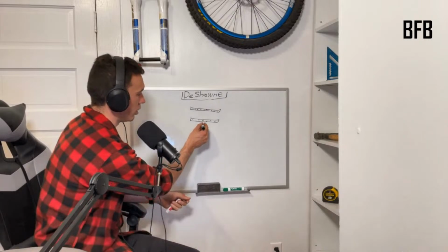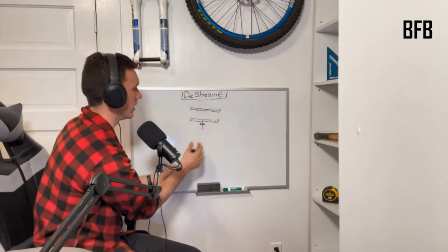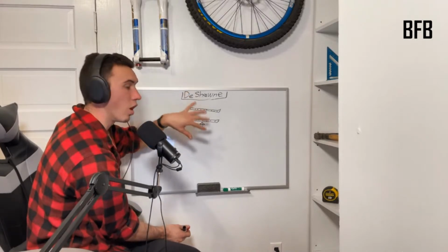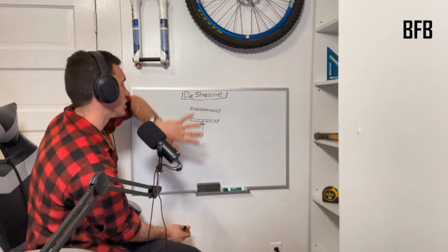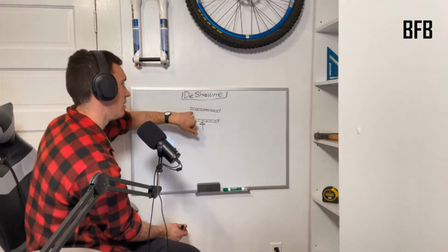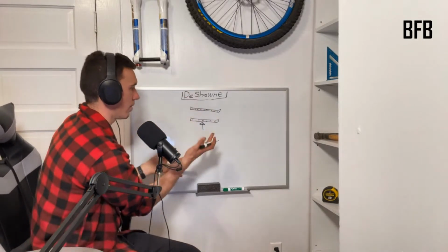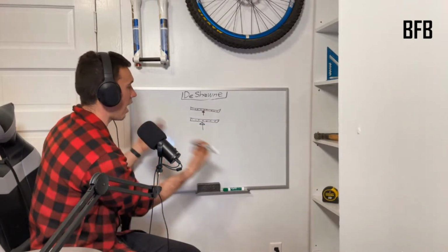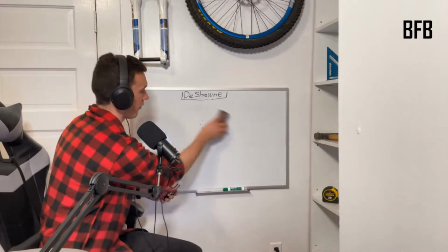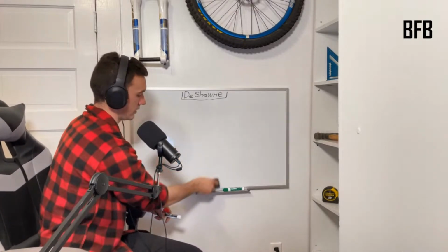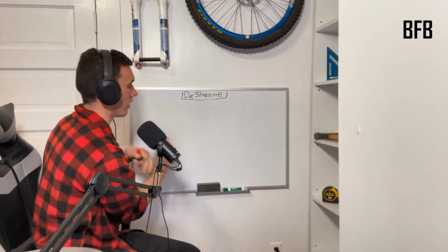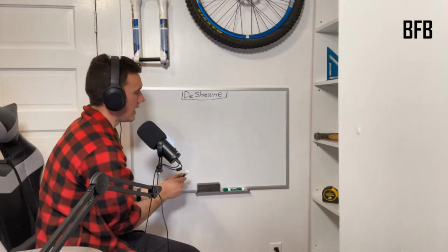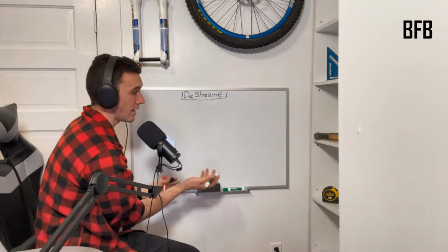Now, if you try to push this one, something happens to it, because it's connected to the nails, which are connected to the oak on top, right? That load's going to be transferred back down the nails to the other one and back into the other one. So they're going to share the same thing. If I push on this, it's also going to be pushing on that. Okay. So expanded out into framing, we take lots of studs and big sheathing panels and we cover them up all over the wall and nail them off in certain patterns. And it gives us a diaphragm.